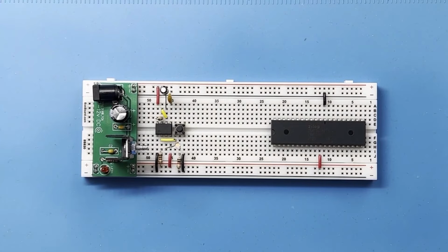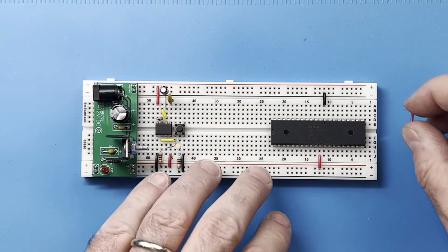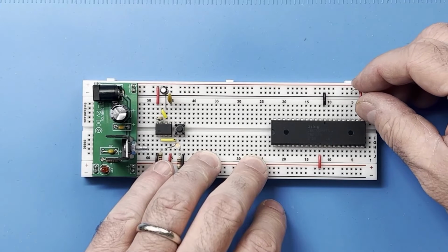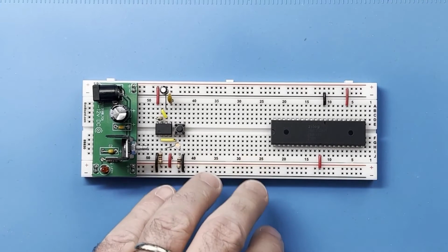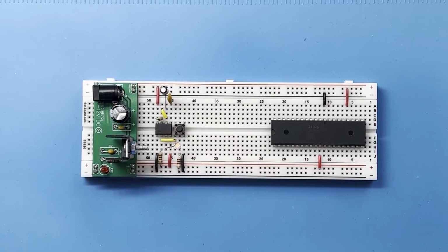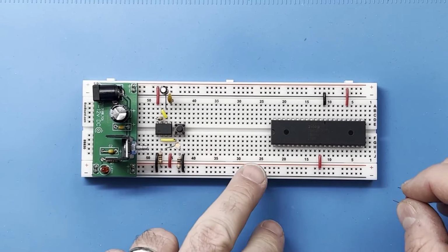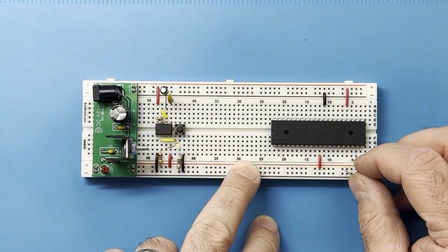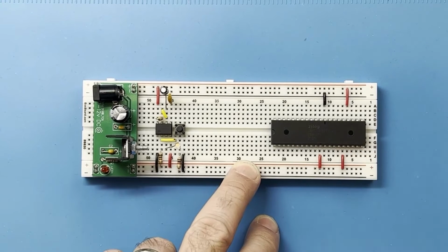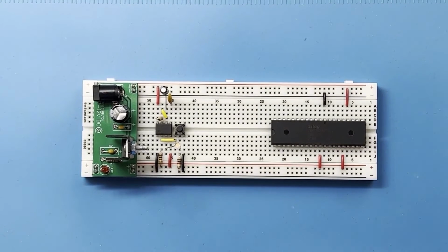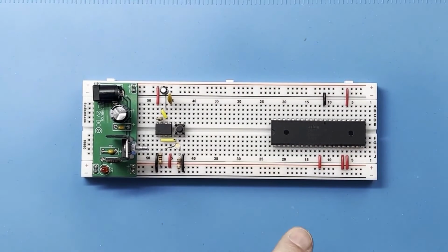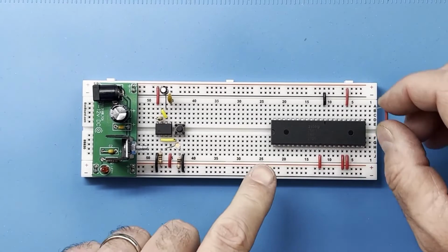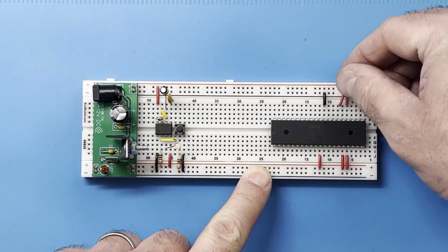And if you remember from earlier, we had several control pins that were active low, and we want to pull those high so we don't wind up resetting or waiting or interrupting. So here pin 24 is going to be the wait line. I'll tie that high. Down here on pin 16 is the interrupt line, and right next to it is the non-maskable interrupt line. Right there, yep. And then we've got the reset pin, which is 26, and I'll tie that high so that we don't just keep resetting in a loop and nothing happens. There we go.